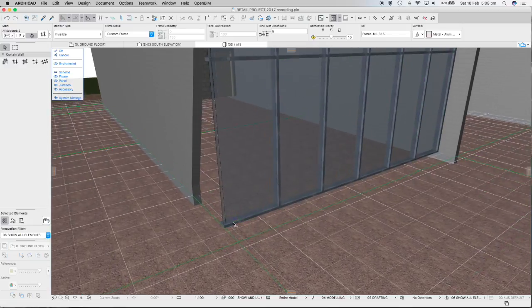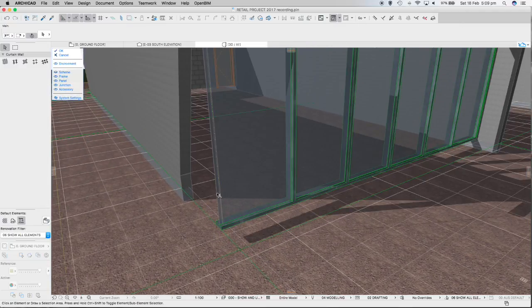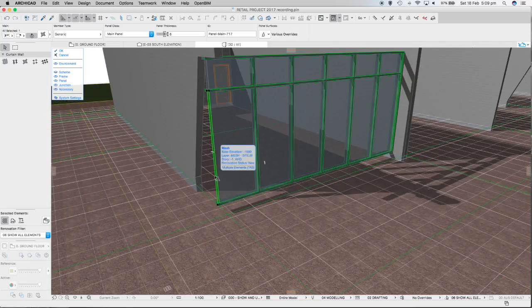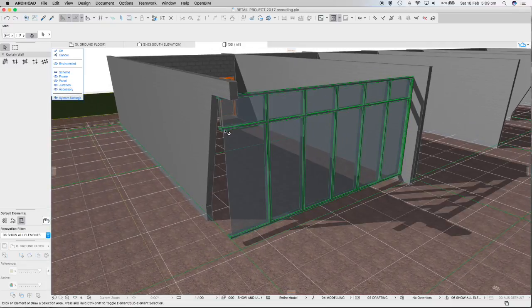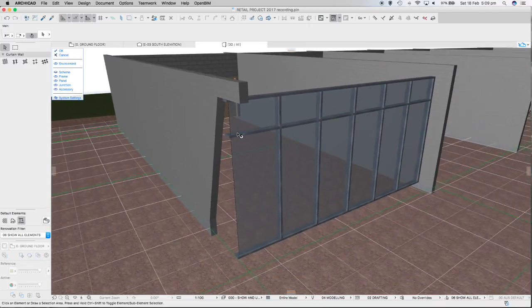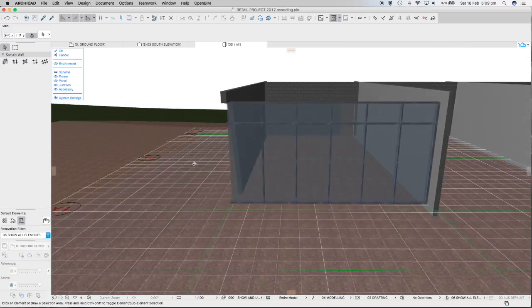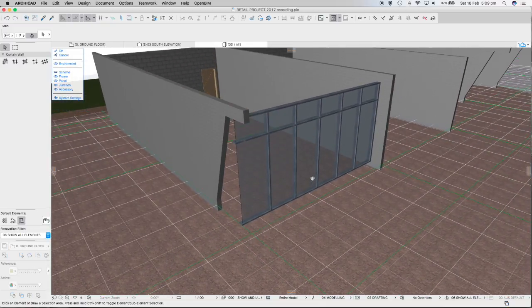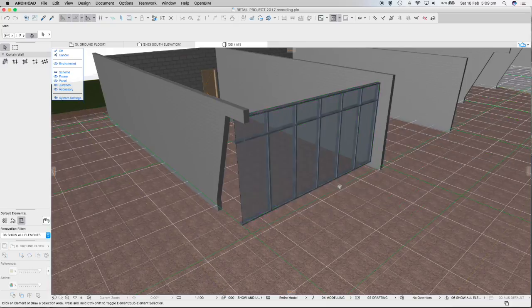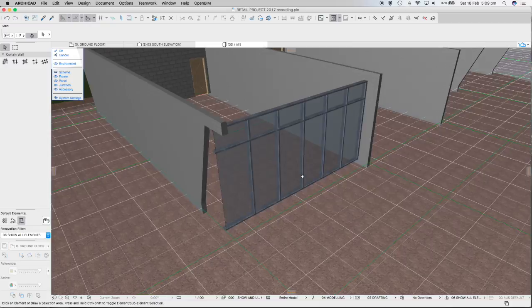And then I want to, I think, this extra little panel that we've got here. Now panels you can delete. So you click on the panel, little tiny glass panel between those two mullions. If we just went delete, that'll give us a frameless corner that we're going to butt join the glass up around that corner there.